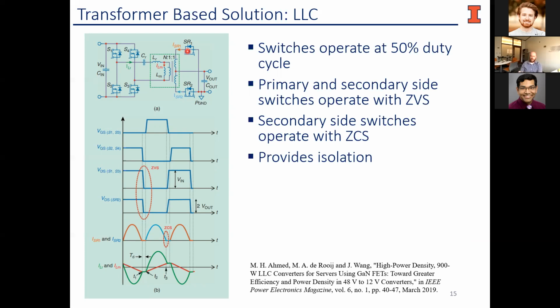Now we still have limitations on this, right? We still have parasitics in this converter. And that's why these converters are still not operating at, say, 13.6 megahertz or something along those lines. They're still operating at something reasonable. But now we also use this structure to provide step down as opposed to using a lot of the energy storage elements. This transformer gives us a way of stepping down the voltage. Essentially this is very similar to our traditional converter, right? We have some sort of chopper stage. It goes through a step down stage with the transformer. And then we have a rectifier stage on the output.